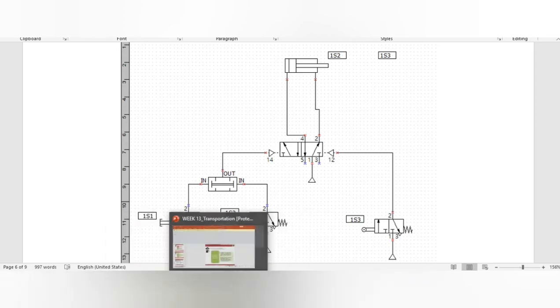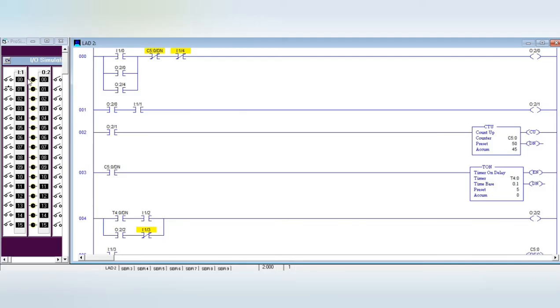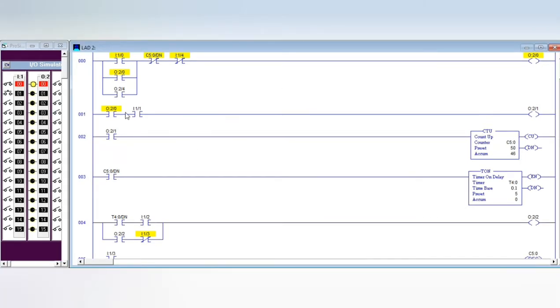So let's see how the PLC diagram works. I'm going to turn on this machine. As you can see, this machine is already on. This sensor detects one can at any time, and we have already done this 46 times, and we need 50 cans, right? So we have to press I11 for 4 more times. As you can see here, 1, 2, 3, 4.